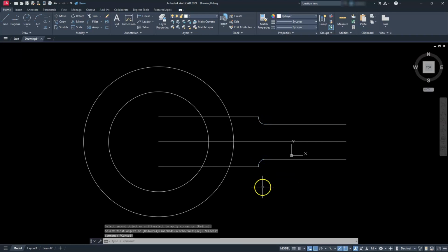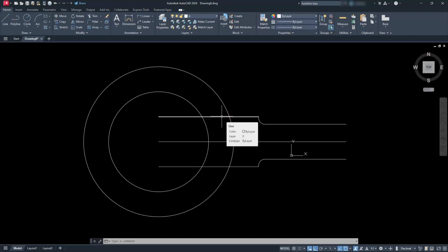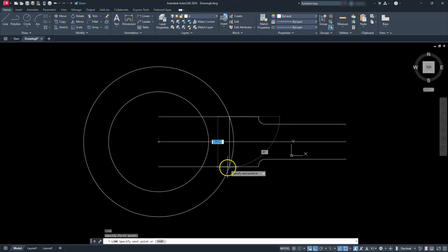Okay. So now for this shape, it actually goes into my C shape here, right? The way that I'm going to create that is I'm just going to draw a line from this intersection going right to this intersection, right? Those are going to be the low points of whenever this thing revolves around. And I'm kind of speaking in terms right now of what I plan on doing. So I'm going to make a revolve that goes around that way, and it's going to capture that.